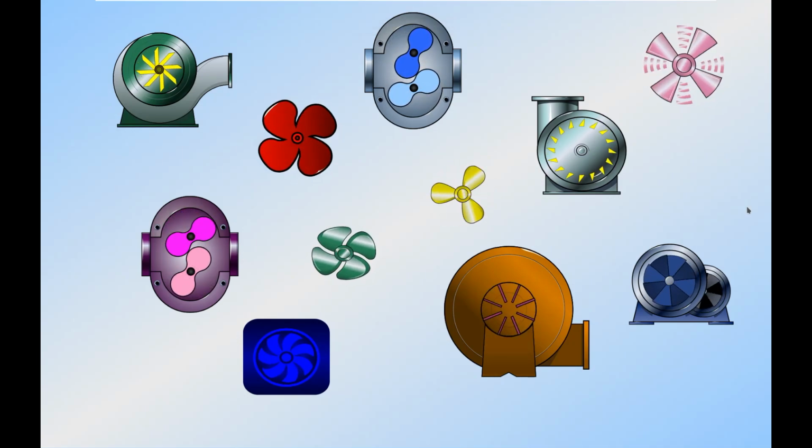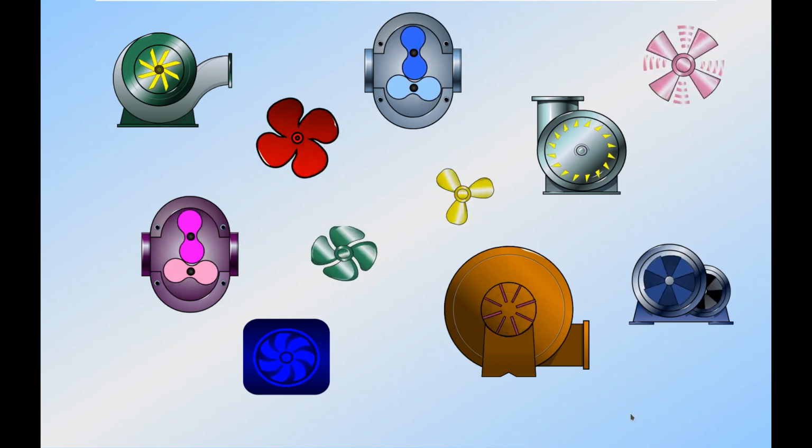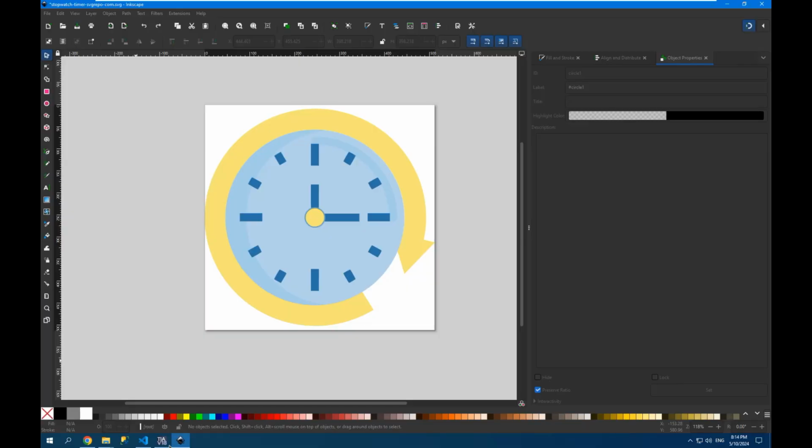Hey everybody! Today I want to tell you how quick and easy it is to do SVGHMI widgets with animation on the clock example. What do we need for that? First of all, we need to set the ID to the objects that we want to animate.